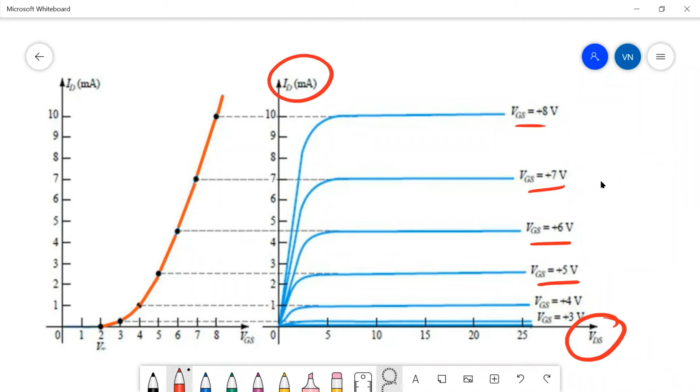And one of the things that you can see is that with the FET, every time it increases by a step of 1 volt, here the distance between the two currents is this. But as we go to the next voltage, you can see it's actually a larger current jump on the drain, and again a larger current jump. And down here you can see it's really small. So what this implies is that there's a parabolic response between the gate voltage and the drain current.